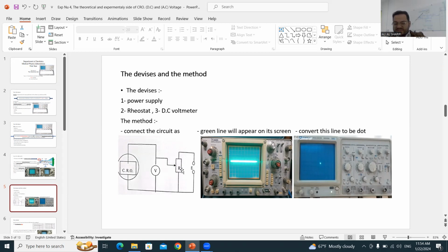And here R is the rheostat, and it will be at maximum. That means when I turn on the power supply at DC, specifically I will work at first at DC, no current and voltage will pass because the rheostat is at maximum. By that, it will act like a wall. Our work will depend on decreasing the rheostat a little bit and taking a look at the voltmeter to see which result will appear. Here, to note, it's important.